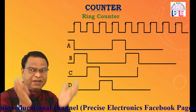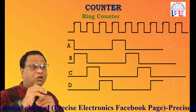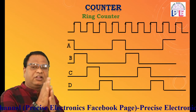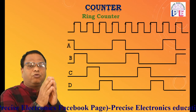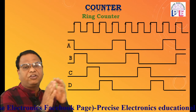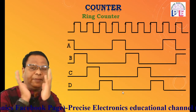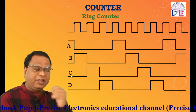So the timing diagram, or the clock diagram, gives an idea of the waveform and how the bits are shifted. That gets clear by using this timing diagram. By using the timing diagram, we can easily understand how the bits are shifted toward the left hand side. So that is the timing diagram, or clock diagram, of the ring counter.